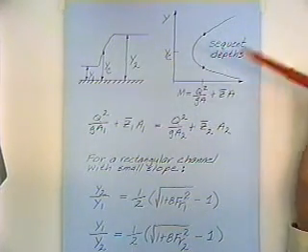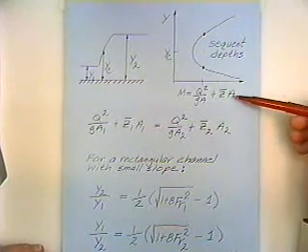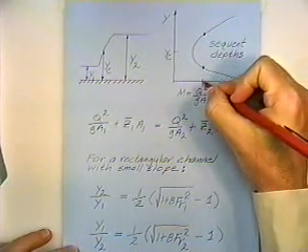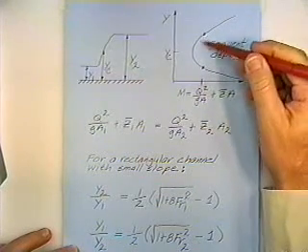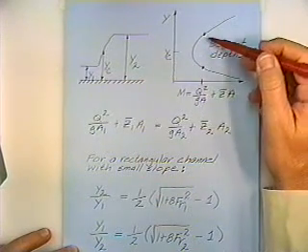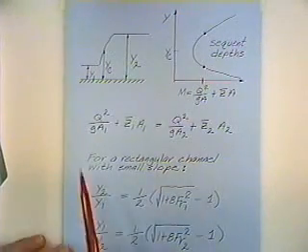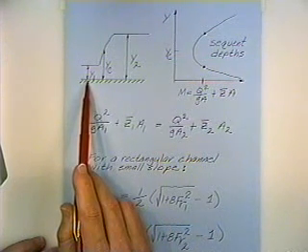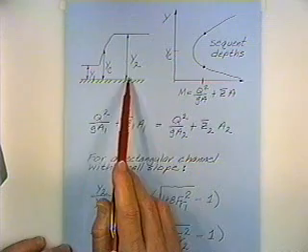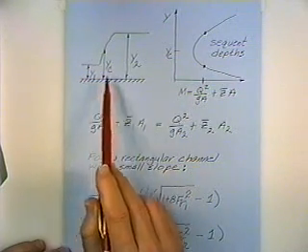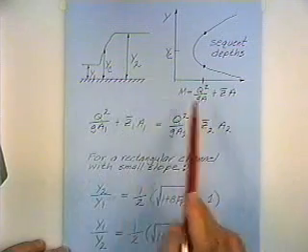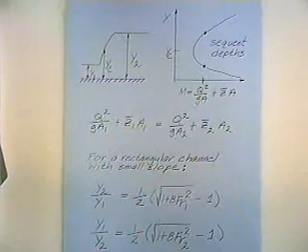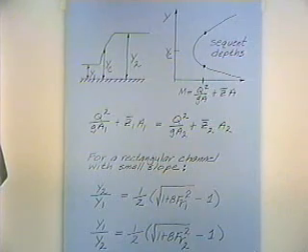For a given specific momentum, I'm plotting depth versus specific momentum here. For a given specific momentum, there are two different depths that have that same momentum. We call those sequent depths. If we apply this to a hydraulic jump, what that would represent is the depth before the jump and the depth after the jump. So we've got the same specific momentum before and after the jump, and the equation holds true in both places. Those are the two depths at which the same specific momentum holds true.